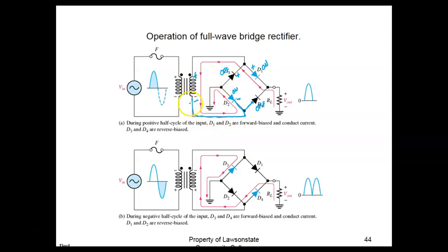Current's going to come out of the negative on the transformer. Current flows negative to positive. It's going to go this way. Can't go that way because it's off. It's going to come over here, go down to our circuit common or circuit ground. That represents a wire. This happens every once in a while. Well, I thought that wire was inside the trainer. It's not. You have to run that wire, guys. But when we use a symbol to represent our common, that's going to be one less wire that I have to draw in a circuit. But what you have to understand, this represents a wire. This represents a conductor.